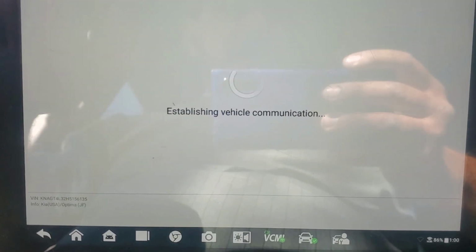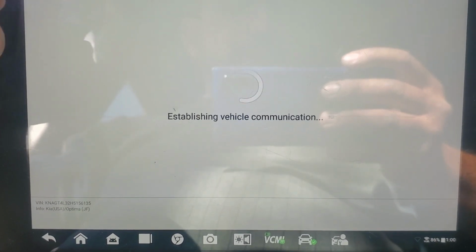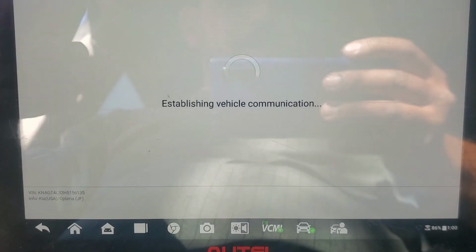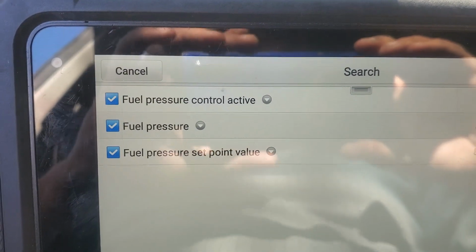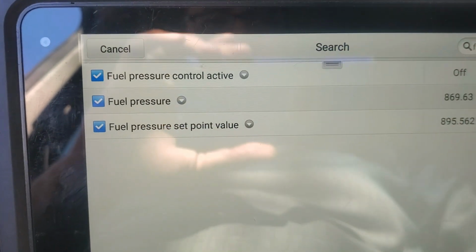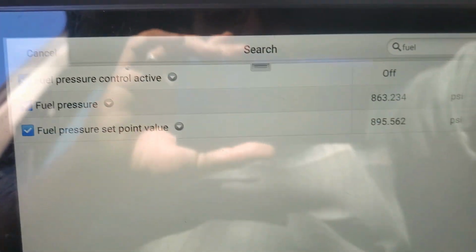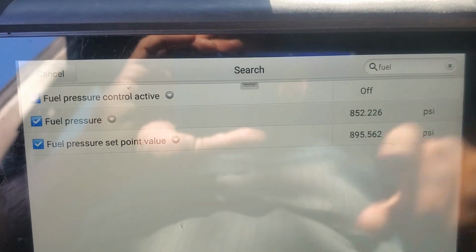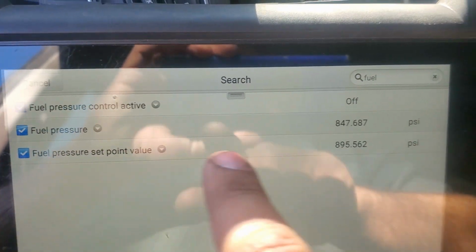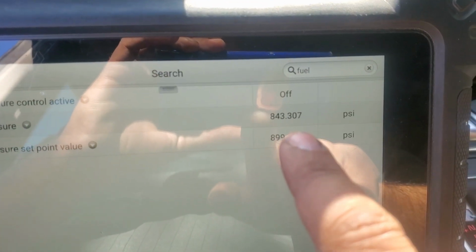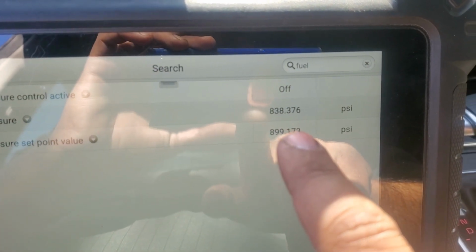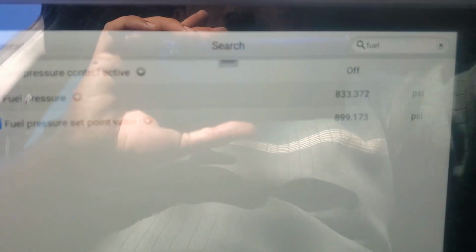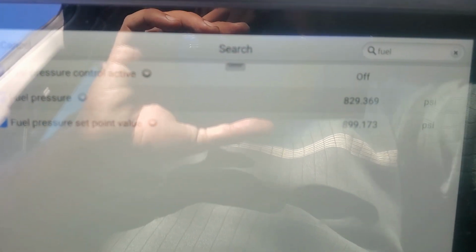Let me arrange some data pads and get you guys back with me. I'm not sure what we pulled last time because the laptop is not with me, and even the clips are not with me. They're at home, but I think we were looking at the fuel pressure, and that pressure was stuck on 80 or 90, but now everything's promising. I just primed the system.